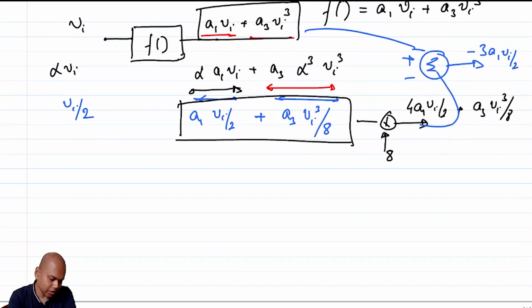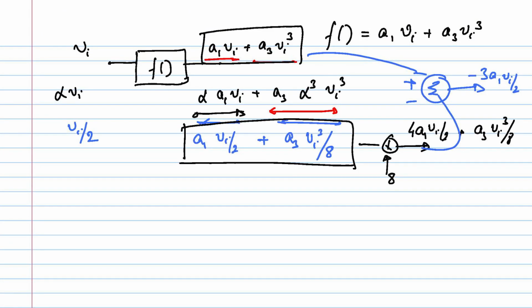Let's concentrate on the fact that we are only trying to mitigate the distortion arising from VGS nonlinearity, that is the GM nonlinearity, the nonlinearity of the output current, not the GDS nonlinearity per se, for the time being. So let's say I have a GM which is distorted.